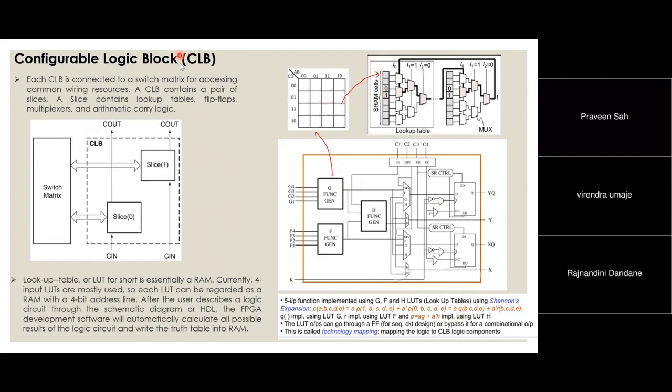So this is what we call a configurable logic block, or configurable hardware. Basically you are changing the functionality by selecting what gates you are using, what flip flop, what mux, and by selecting the interconnects, which flip flop is connected to which gates. So by changing the hardware, you are changing the functionality. I don't want to bring software in, because that will confuse you. So basically you are configuring the hardware.